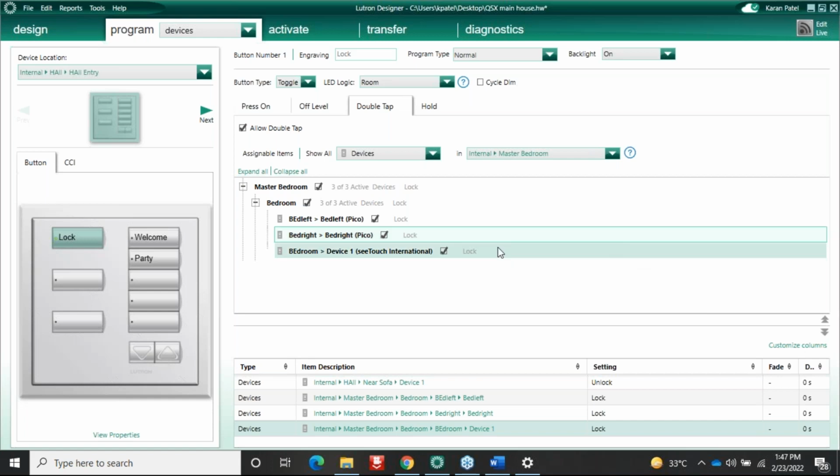Okay, so many times people ask me what is the use of a very long fade time, like maybe 1 hour or half an hour. What is the use of it? Typically in the evening, if I want to light up passages, like a hallway or the balcony lights, I use a higher fade time. At sunset I trigger that event and the light smoothly fades from 0 to 100%, which gives a nice effect. Artificial light is coming in and the natural light is going away, so it gives a nice balance.